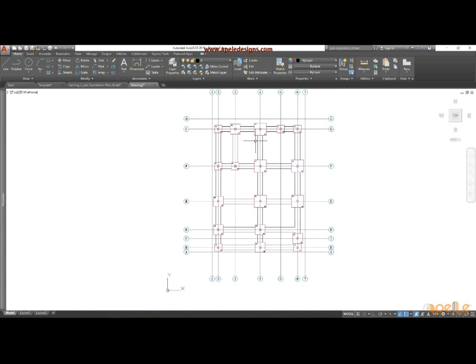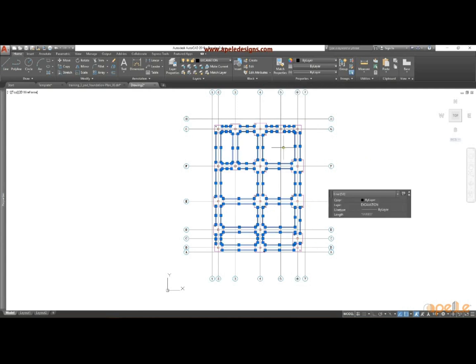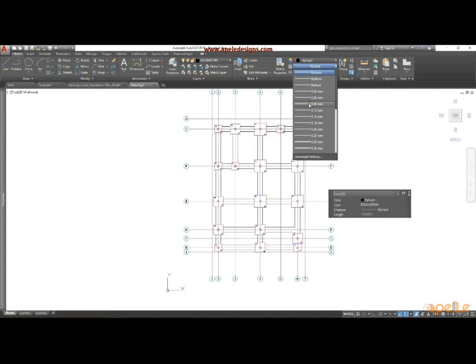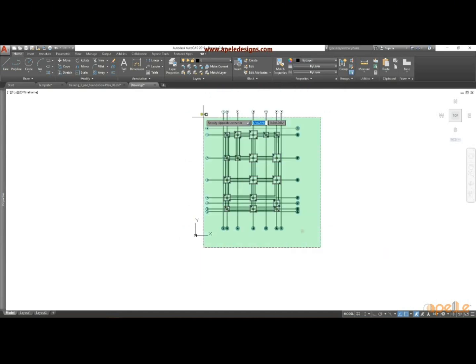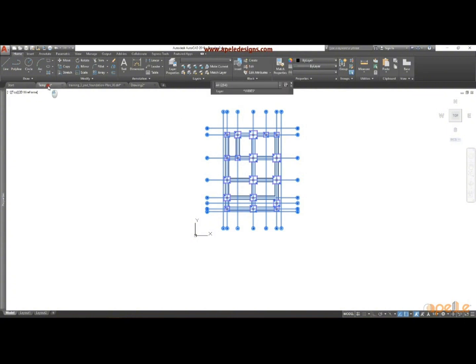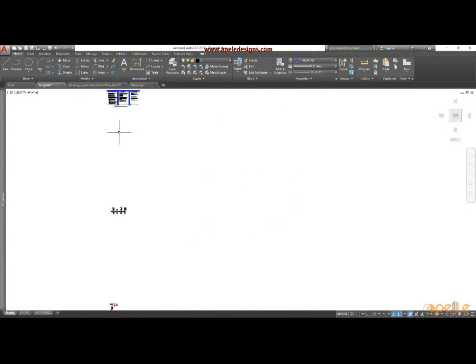Now, why do I have to place each element in a layer? So that you can actually make a modification to all the elements at the same time. Now, I can click on this, just one, and right click, select similar, select all the lines I need. So I can either make them a little bit thicker, make it faint, it's all my choice. But I'll copy this, the entire project, Ctrl C, come to my template, paste it at the bottom here.